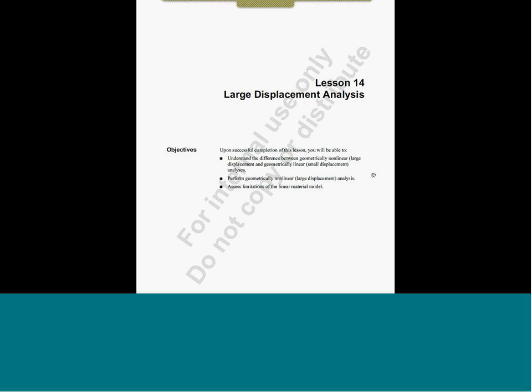About both of these, that is the chapter on adaptive meshing, and the more controversial one is this last chapter on large displacement. Now, large displacement is a non-linear condition, and logically I would have expected it to be present in Simulation Premium only, but we do have it here. What it can do and what it cannot do is a huge matter of discussion, and frankly does not end. It's a bit of a complication.